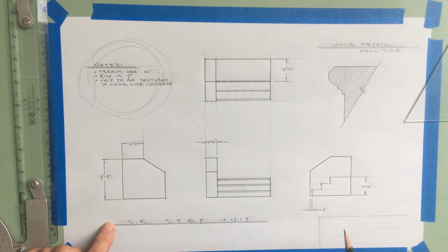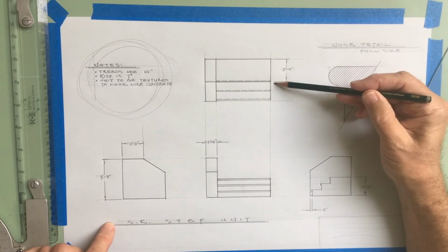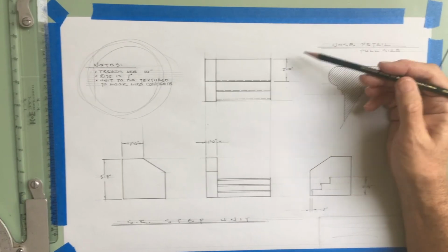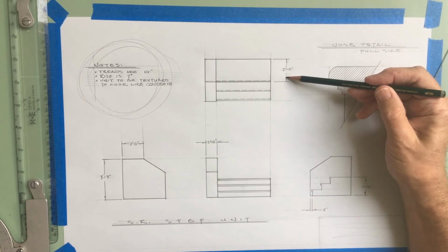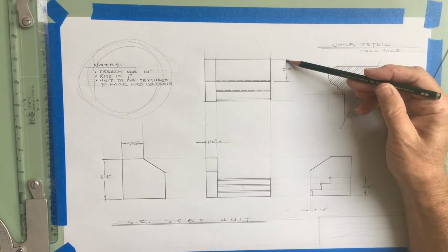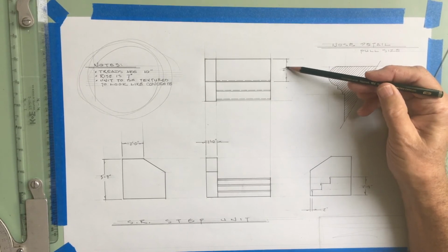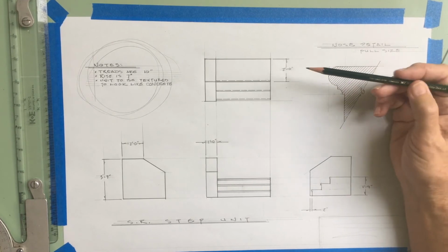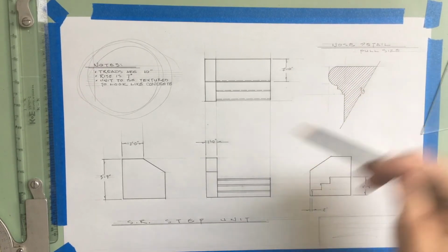Also, there are some dimensions. These lines are called extension lines, and they extend the size of the object out away from the object to a place that's convenient, usually 3/4 of an inch away. And this is called a dimension line, and it's a line with arrow points on each end that's broken, a space in the middle where you put the dimension. And remember, in the theater, we're doing dimensions in feet dash inches. So it's 2 feet dash 0 inches.